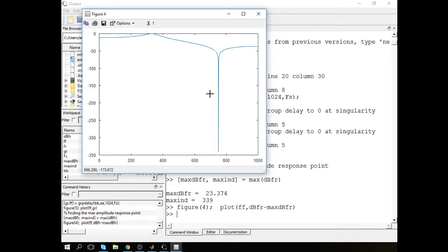Okay, how to scale the system? This is just the plot. You actually divide the numerator part. So basically, you will be affecting this value here. You rescale this value, meaning that A0 must be 1. So it means that you can scale only the numerator values, the feed forward values, the Bs.